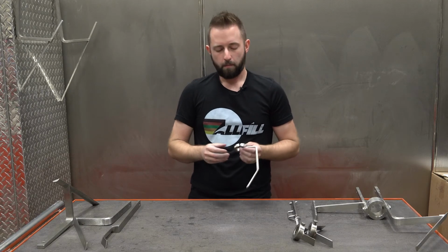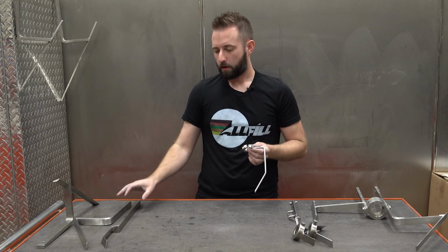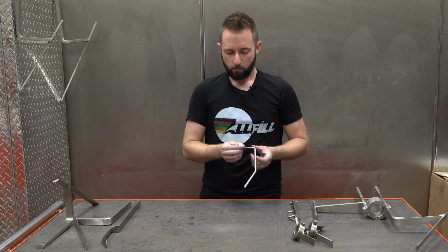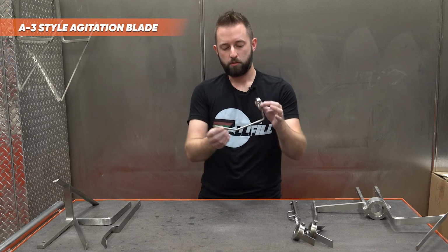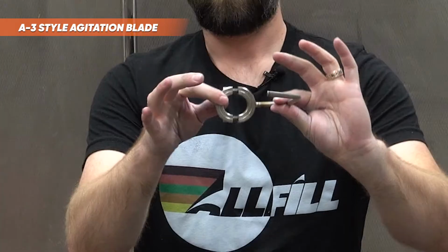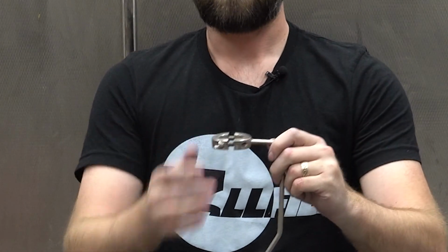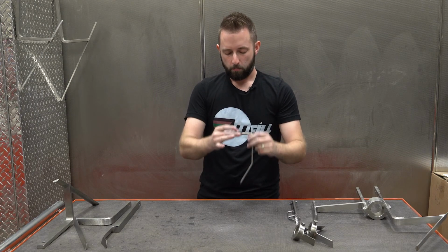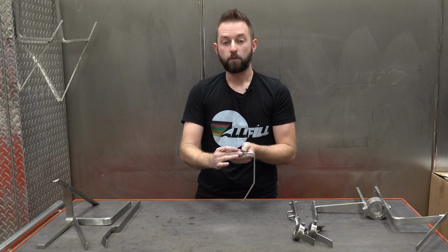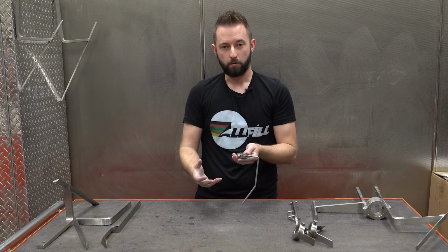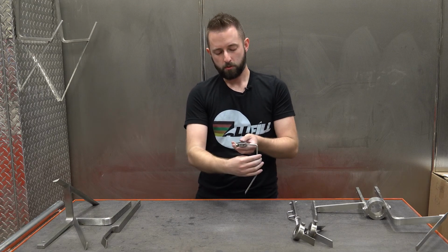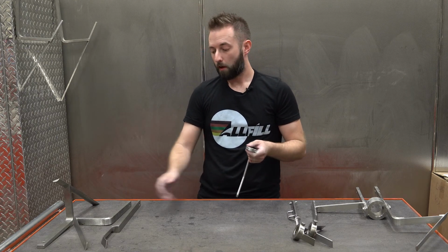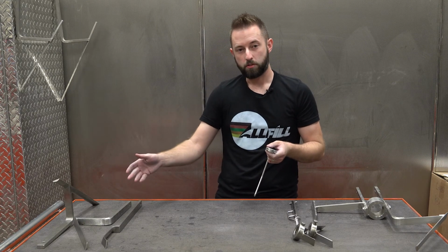Having tight centers like that and being unable to use standard agitation complicates things because there's a lot of products that still need agitation in that design. So that's when we can turn to what we call an A3 style agitation blade. And these, with the help of a split collar, will connect to the auger shaft or the stem of the auger in some cases and be really targeted agitation in a very small footprint, which helps with a multi-fill because of the small centers. So essentially you can have agitation targeted directly around your auger and get the agitation you need without having interference from one of these larger style agitation blades.